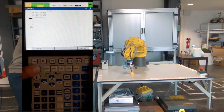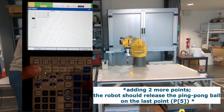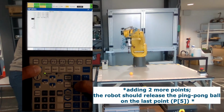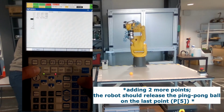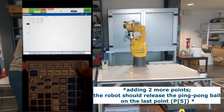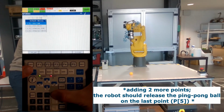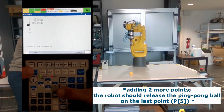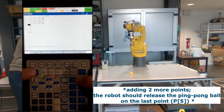I will now define 2 more points. One is just to lift the ball out of the table, and the last point will be the point where the robot will drop the orange ball. Do not forget, every time you want to move the robot, you must be pressing the deadman switch and the shift key, otherwise, you won't be able to move it.